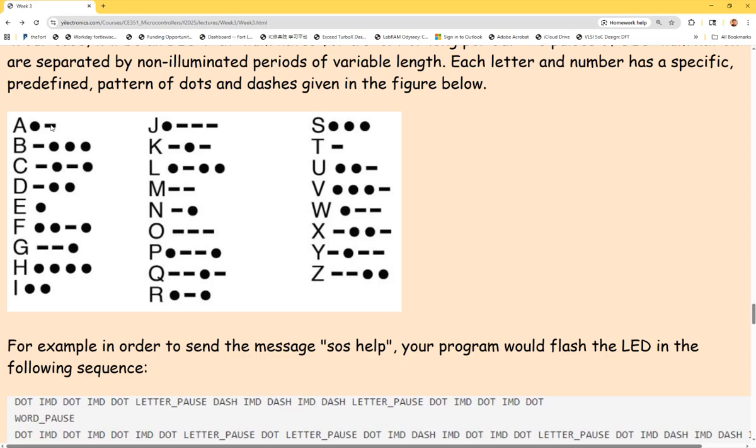So how do we do that? It's basically just you turn on that pin, because that pin is driving that audio amplifier. It's directly connected to it, you don't have to modify anything, and then to the speaker. You have to connect the speaker to that output. So if it's on for a certain time delay, it's a dot. And then you turn it off for what's called the inter-marker delay.